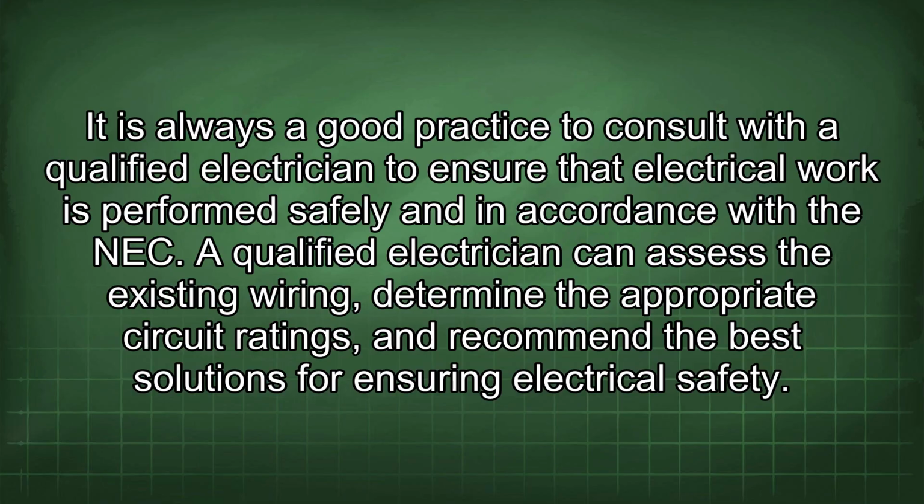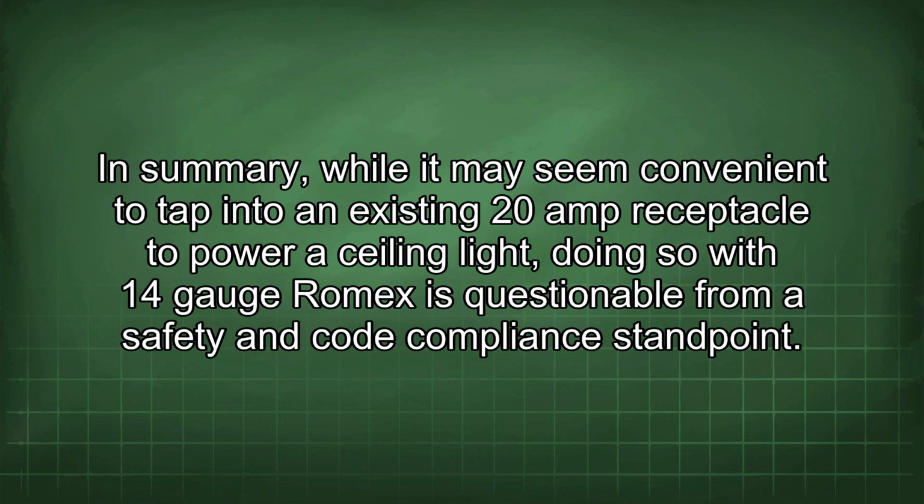A qualified electrician can assess the existing wiring, determine the appropriate circuit ratings, and recommend the best solutions for ensuring electrical safety. In summary, while it may seem convenient to tap into an existing 20 amp receptacle to power a ceiling light, doing so with 14 gauge Romex is questionable from a safety and code compliance standpoint.